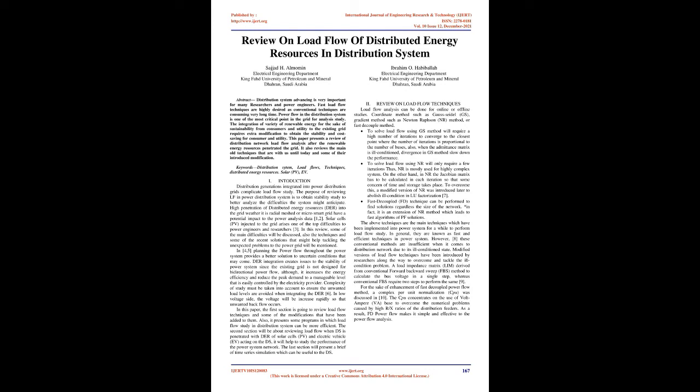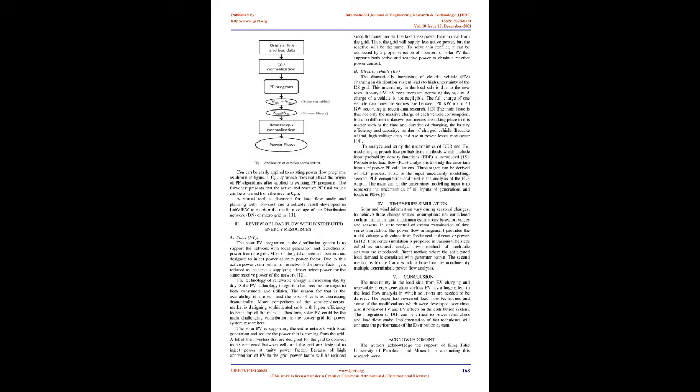Load flow analysis can be done for online or offline studies. Coordinate methods such as Gauss-Seidel, GS, gradient methods such as Newton-Raphson, NR, method, or fast decoupled method. To solve load flow using GS method will require a high number of iterations to converge to the closest point, where the number of iterations is proportional to the number of buses. Also, when the admittance matrix is ill-conditioned, divergence in GS method slows down the performance.